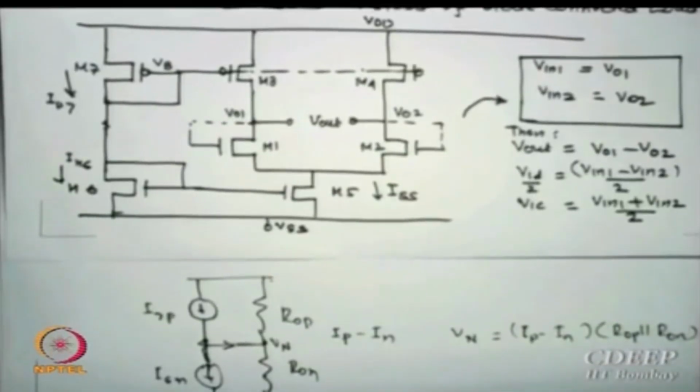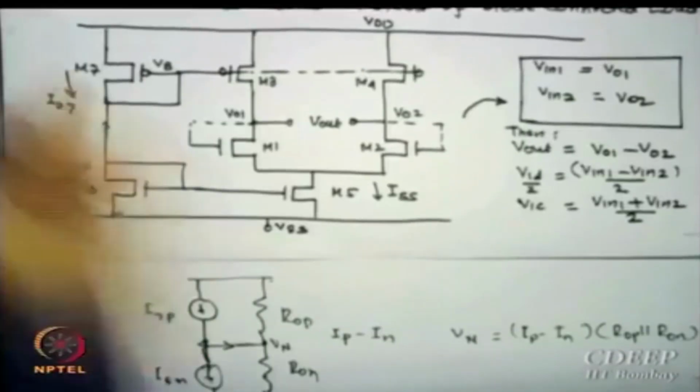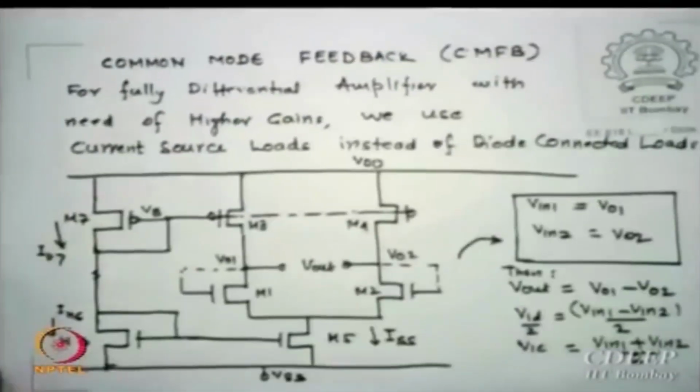Normally what should have been there? Zero drop across, there are two current sources, no drop there, they have balanced out. But it may happen that the P channel current may not be exactly the same as the N channel current, and because of that this node voltage is not at 0. Is that clear? Now this is a worry which occurs in real life, it is not something I am thinking about as a new thing.